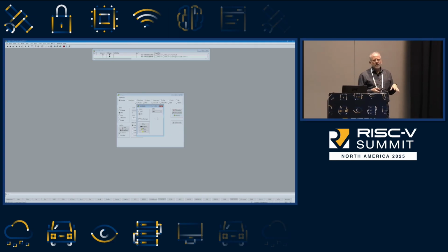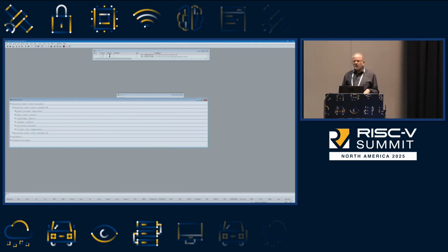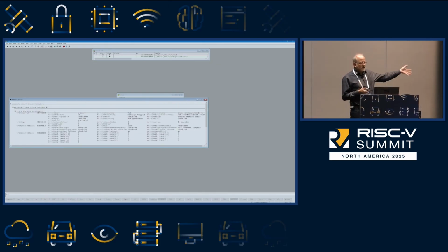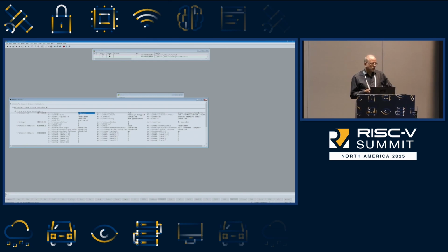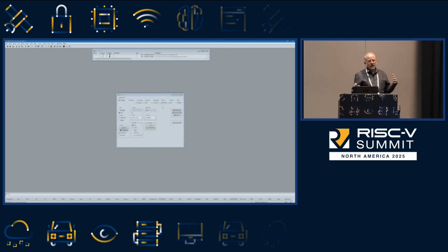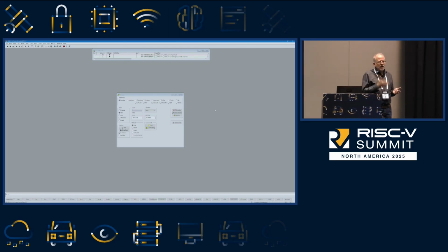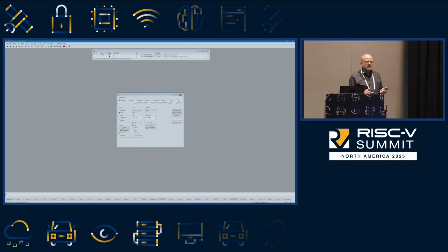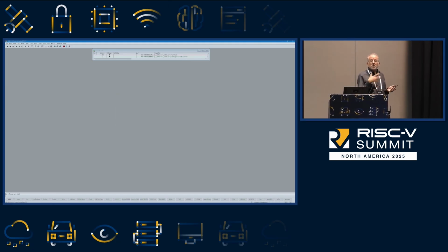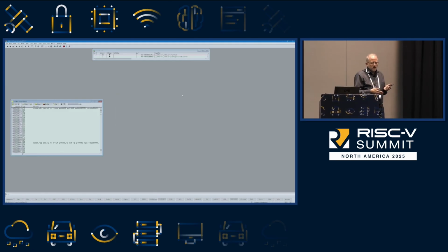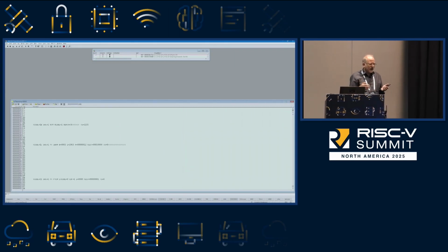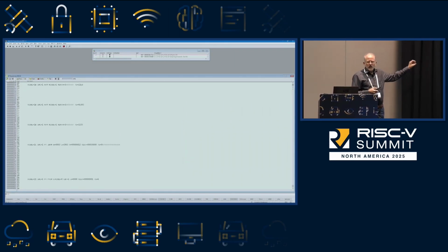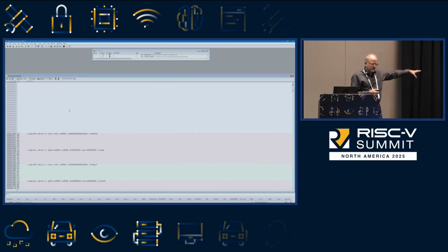Next, they're going to show you the ability to turn on and off timestamps. Lauterbach tools will actually give you access to the registers, and that's what this window is, showing that it's N-Trace. And we're going to actually start capturing things. So Trace, I get this question from customers. Trace doesn't capture every clock cycle. What it does is it takes milestones. You can tell how long it takes between those milestones because there are counters and so forth. But what you're seeing here are the trace packets. This is the low-level stuff that's coming out.